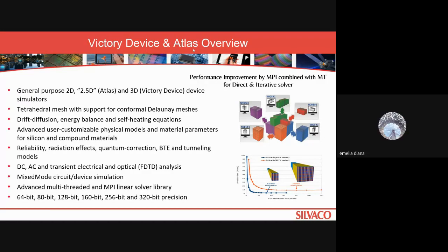Atlas is our latest product. It generally supports 2D, 2.5D and 3D device simulation. We also support complex conformal mesh and also narrow mesh. We support drift-diffusion, energy balance and self-heating kinds of equations. We also support customized physics-based models and customized material parameters for silicon and also for compound materials. We support quite good reliability simulation, as I mentioned before. We support hot carrier and NBTI simulation.